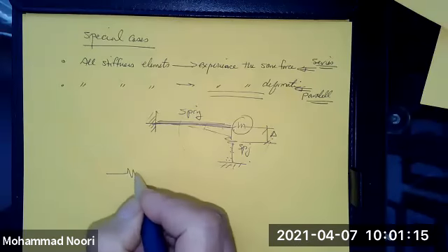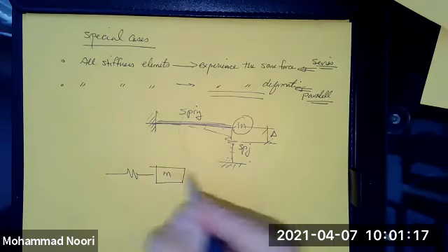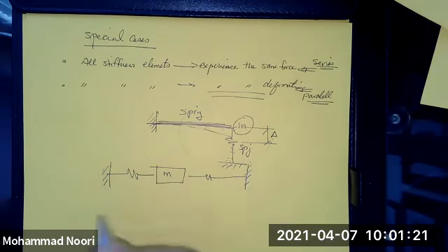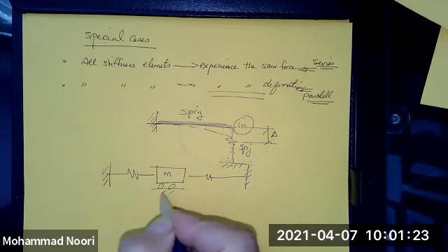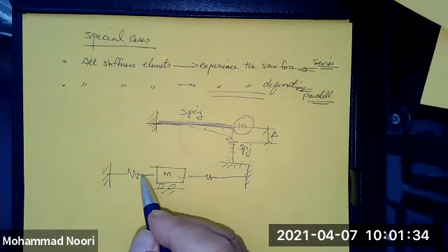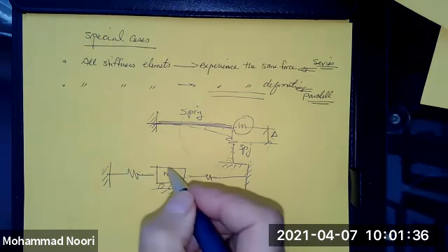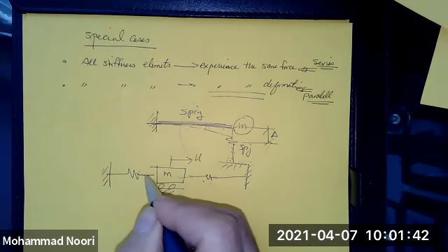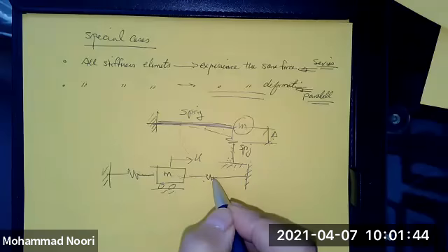So we use this concept to add these up. Or you may have something like this. In fact, this is an example in the book. Seemingly, these two springs are in series, right? Wrong. Because you do not know if these experience the same force. What you do know is, as this mass experiences the displacement, both of these experience the same deformation.